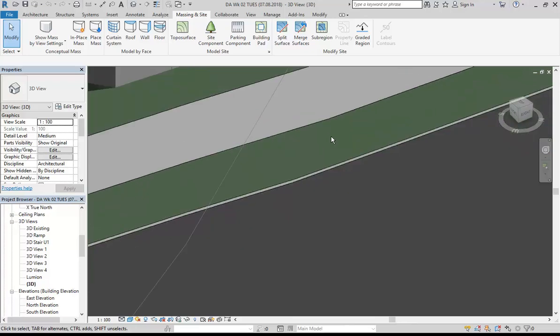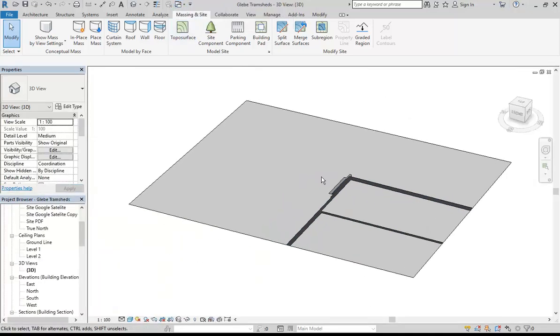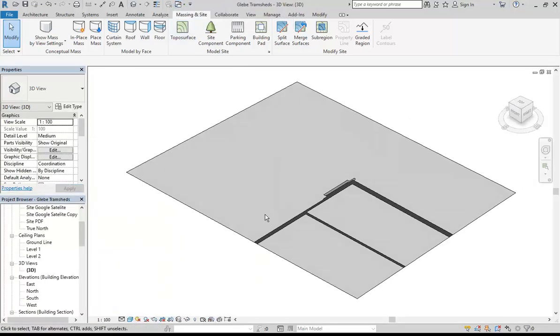You can grab that sub-region and just change that. So you change the topo surface. The original surface does all the heights. So even though you wouldn't put in that detail, you will want to change the heights a bit. So here it's all flat at the moment. So I'm going to now just show you that we can still change the height.